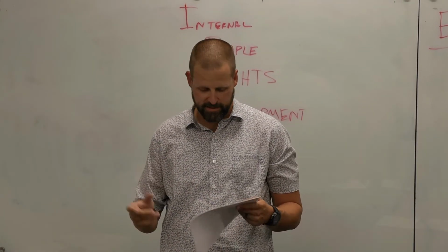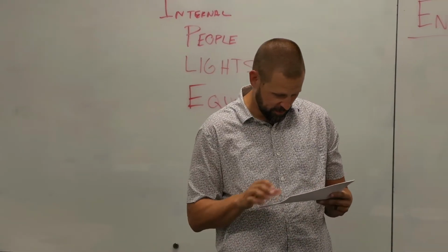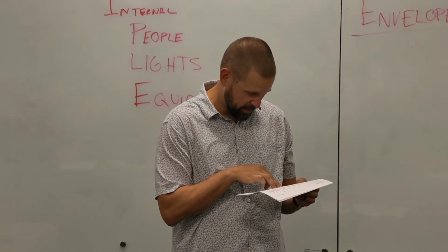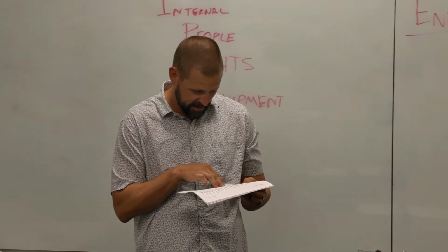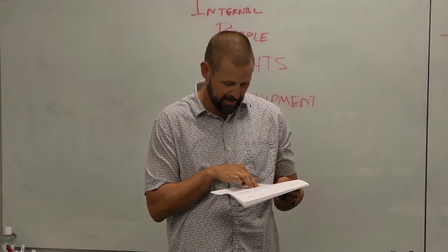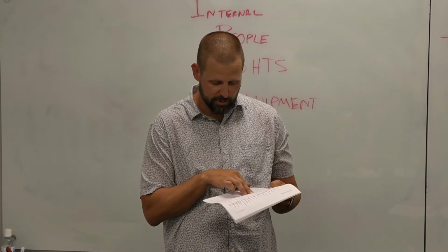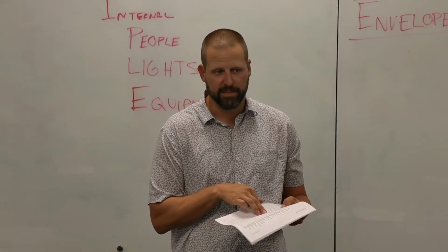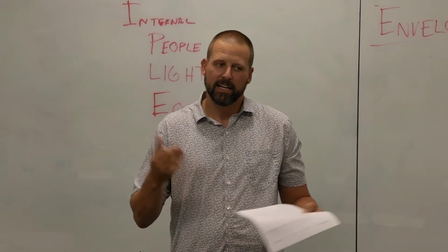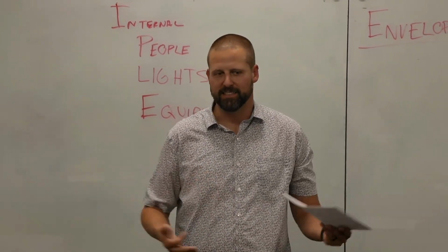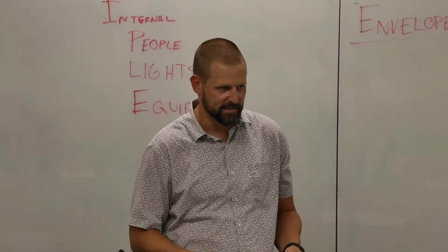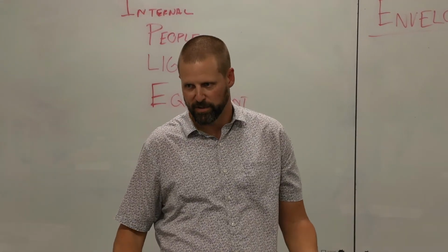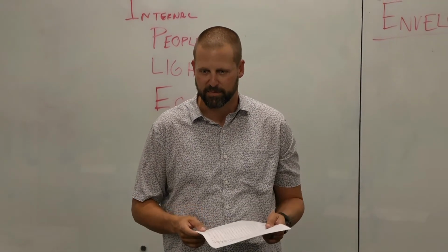or we will add some factor to the cooling dry bulb for heat island effect. So for Los Angeles, if you look at the 0.5% for Los Angeles County, whatever it's for, you'll see 92. Usually we're designing outdoor equipment for at least 95. To go above that wouldn't be unheard of either. You could make a case for setting it the same as that. It's just another place we have safety factor that gets more to equipment selection, so spoiler for next week, but is in this spot.